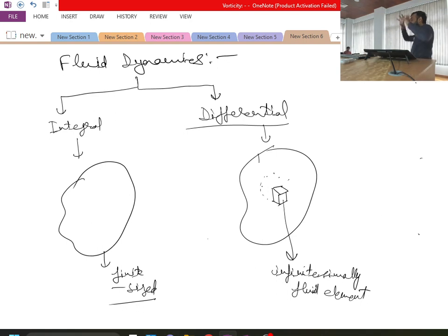And at the entire inlet or entire outlet, all other fluid properties such as enthalpy, internal energy, and entropy remain constant. On the contrary, in real scenarios, because of the viscosity of the fluid, if you have a pipe inlet, then velocity cannot be the same at every point. Near the wall velocity will be 0, at the center it will be maximum, and at other places it will depend upon its location in the plane.